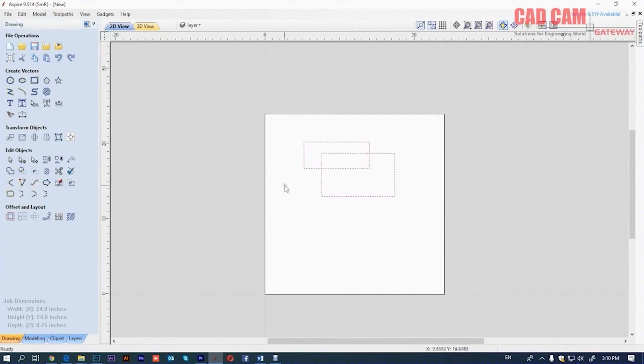In the same way, you have this command here. Before this, you saw the subtract command. Look, I selected one object, then the second one, and as soon as I use the subtract command, the latter object will act as the trimming entity for the first one. I select this and make it the trimming source. When I use subtract, this part gets removed from it.